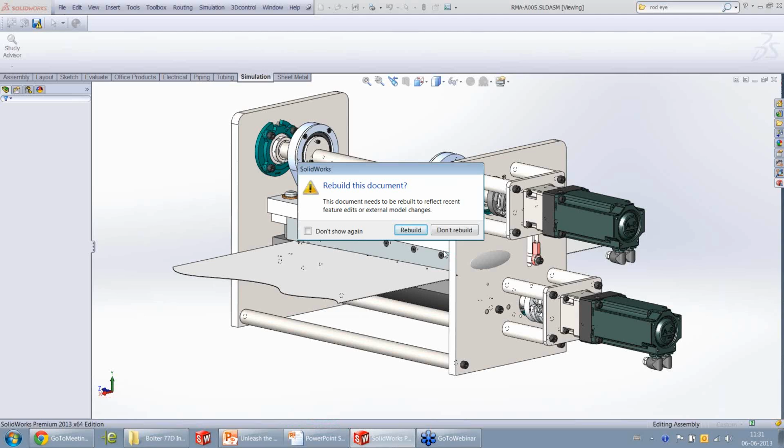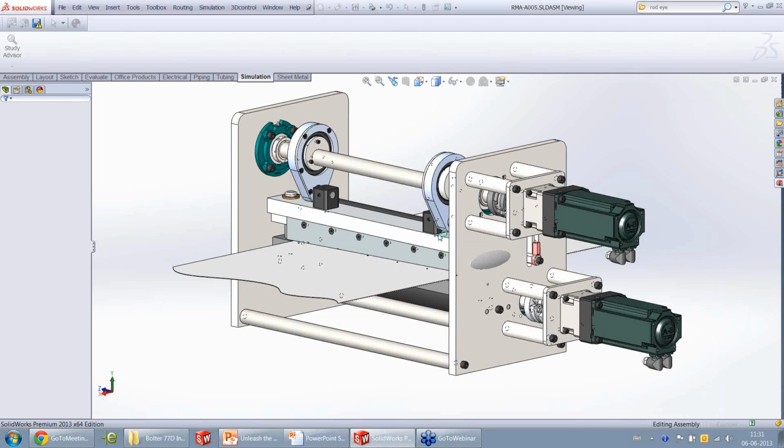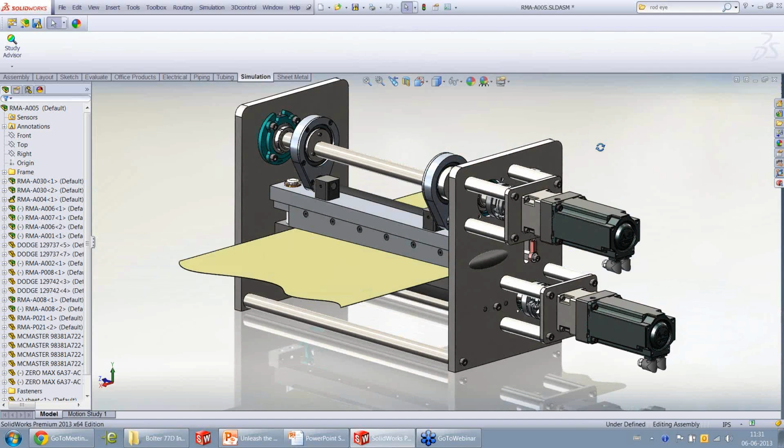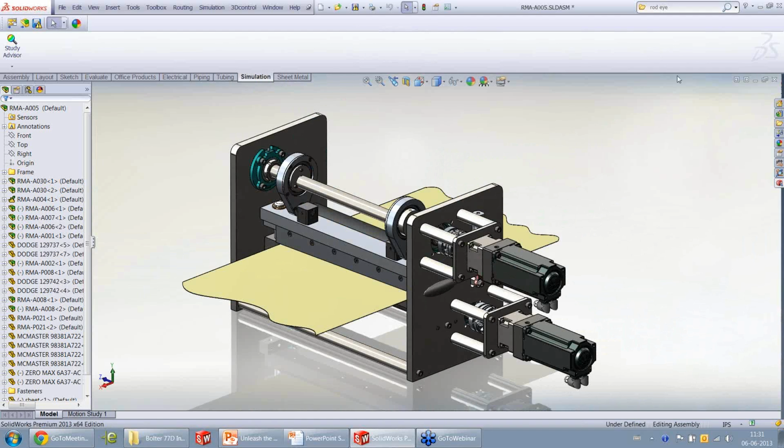We'll just assume that we all need tolerance stackup analysis in order to get our fit and function right. SolidWorks is capable of calculating your stackups at an assembly level, but you need to have SolidWorks Premium for that. SolidWorks Professional and Standard do not support this.